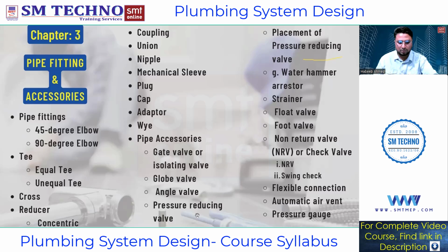If I talk about IPC and UPC, they say that within the water main, the main pipe, the riser, when the water is allowed to fall free from the top, for example, we have a tank at the roof level and the building consists of 30 floors, and the water is allowed to fall free from 30 floors coming down to serve the floors below.